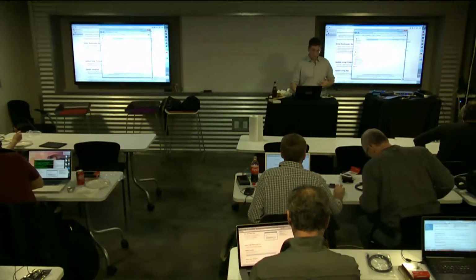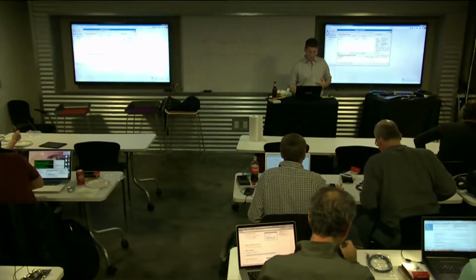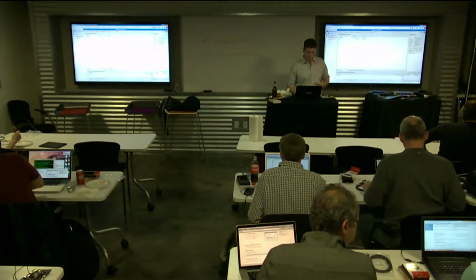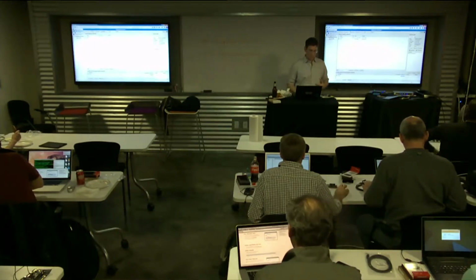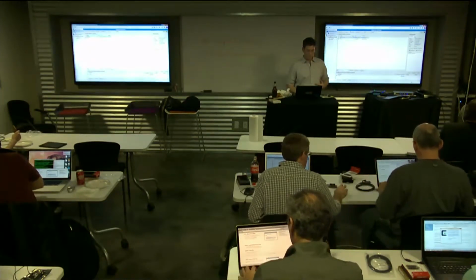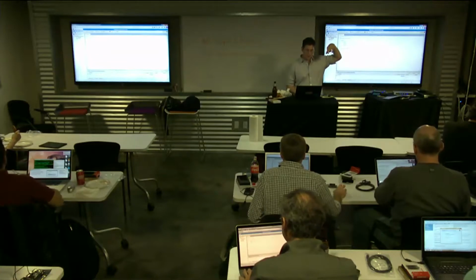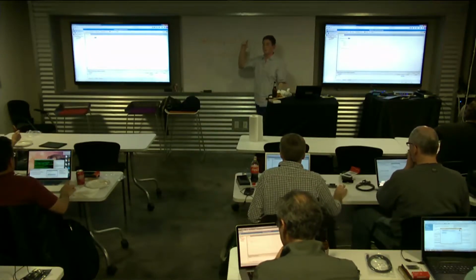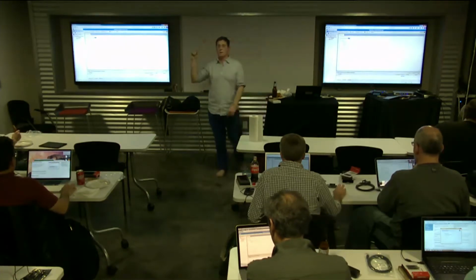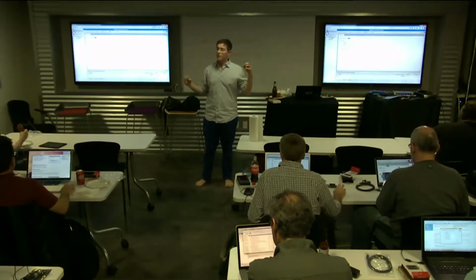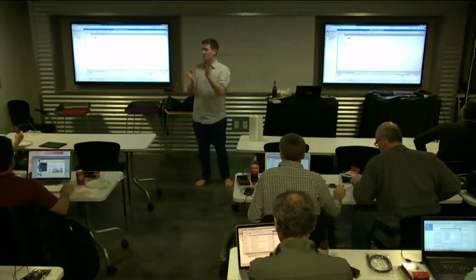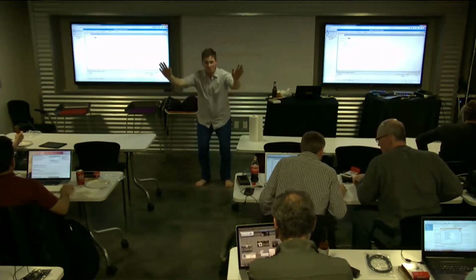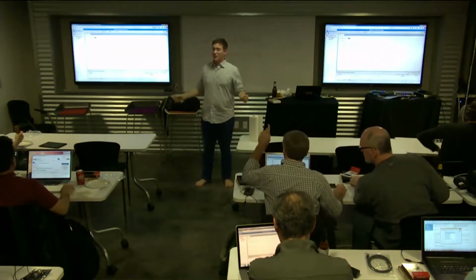In that code, if you look at it in the main file, you just have it available. This LED1, there's also an LED2 and an LED3, which hook up to R, G, and B. So try to make it flash three different colors, and then try to make it flash different colors that are amongst those three different colors. Go. For everyone who's having issues, raise your hand.